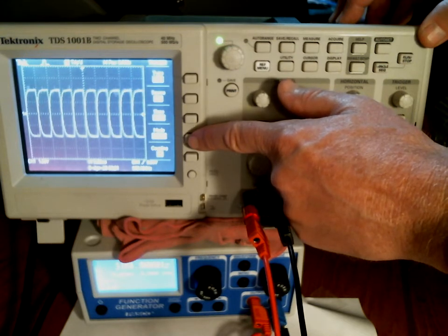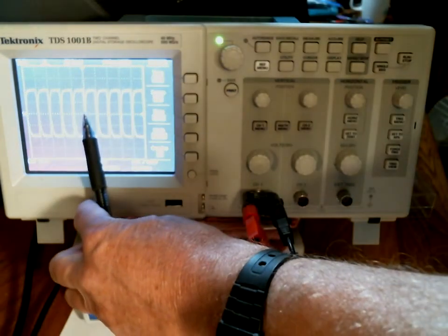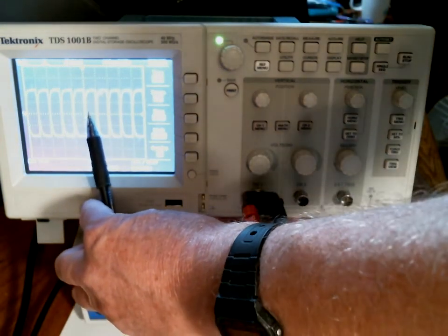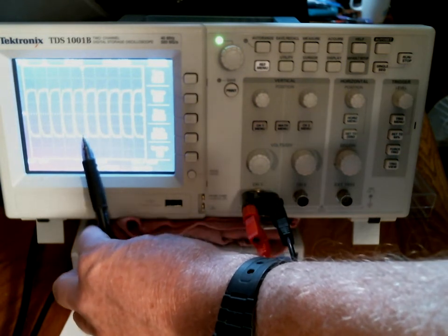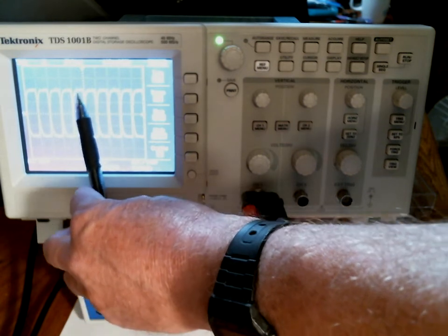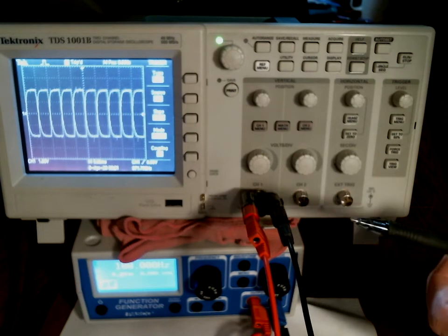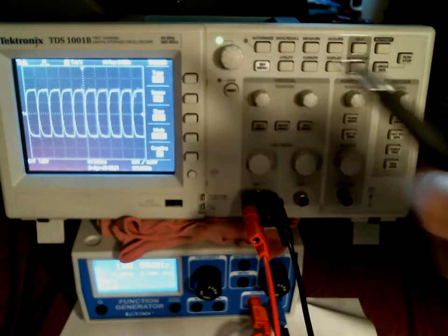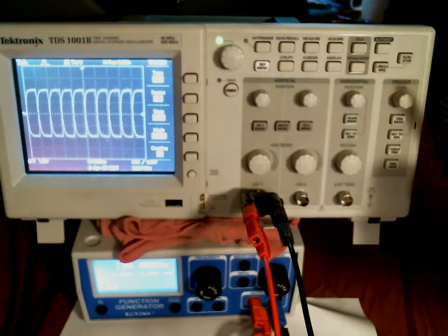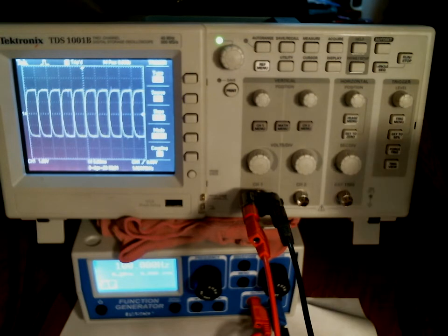And now what's happening here is it's triggering in the middle of the scope, which is what happens on a fancy modern digital scope like this by default. But sometimes it's triggering when the signal is coming up, and sometimes it's triggering on a downward slope. And that actually should not happen, because here this says slope rising. However, what's happening is I have enough noise on this signal so that the noise can sometimes cause the slope to be the opposite of what it should be. So I want to get rid of some of that noise.